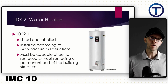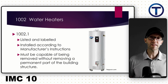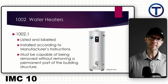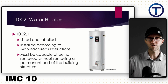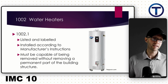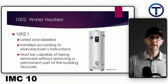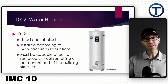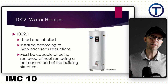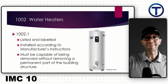Let's look at 1002, which focuses on water heaters. It says specifically that water heaters must be listed and labeled. Listed meaning that they meet certain manufacturer standards and that is labeled on the appliance itself. They must be installed according to manufacturer's instructions. Now, more than any other chapter, I think this is so applicable because they could write an entire book about how to install a water heater or a boiler, but the manufacturers already did that.